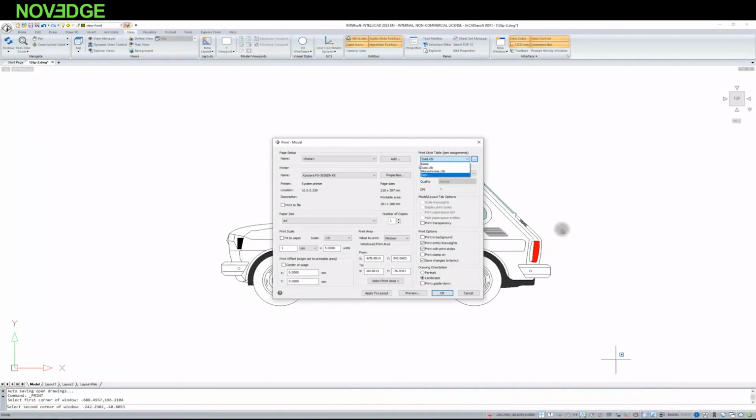And when defining the layers, of course, I specify the thickness of these elements. However, I draw in colors because it is more readable for me. And that's why I chose a monochrome style later. If I do not want to have a color printout because I have, for example, a black and white printer, then all colors are automatically converted to black and printed in monochrome.